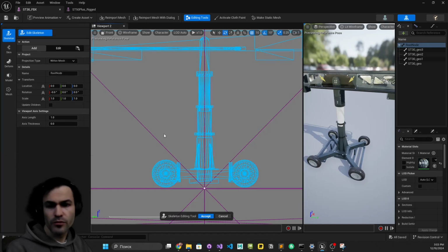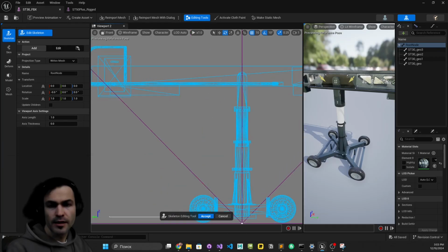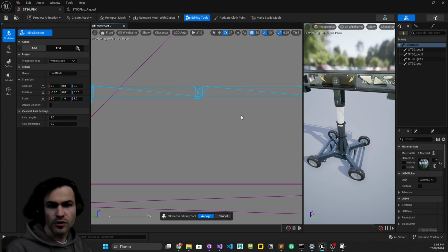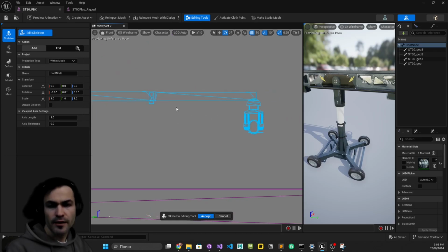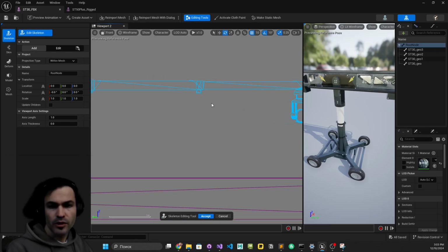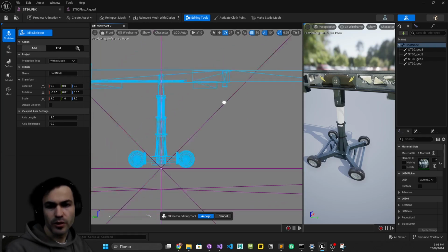So let's start with the root bone, and then from here we need to create some column joints, and then we need to create some beam joints. You see there is the division of each section, and this section should be able to move back and forth, inside and outside of another beam, so that the crane could change its length. And there is this head part and neck part, so we need some rotation here. So we need pivot points for that.